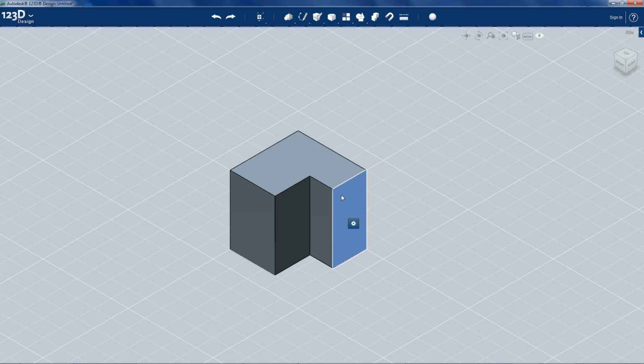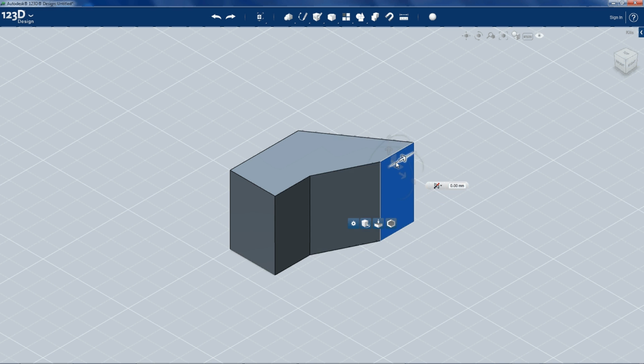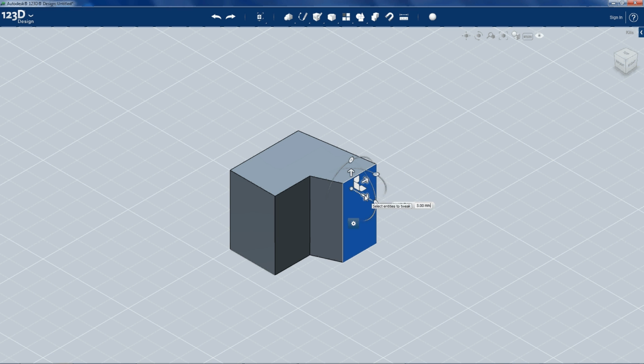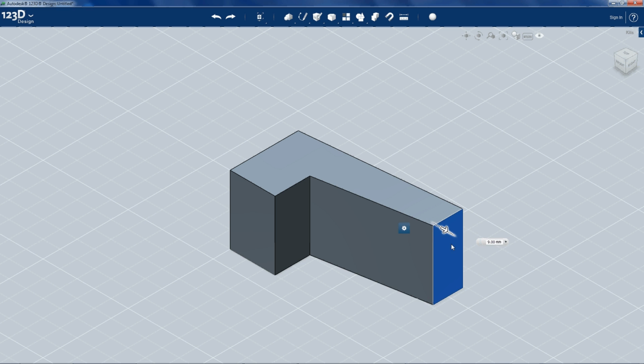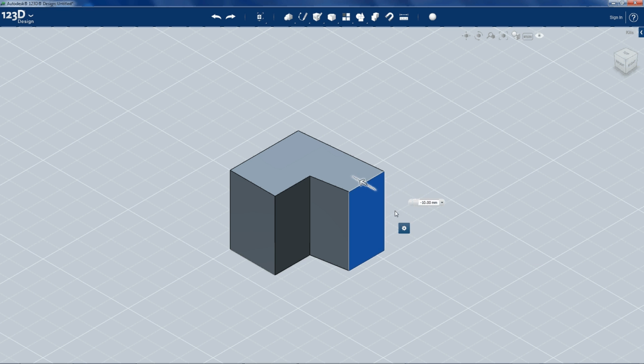So in this case, I'll select this plane, go down to my tool menu, and you see that here's a tool that says tweak. So if I click this guy, I can really do some pretty cool manipulation of this shape. If I try it again, sometimes you have to click twice to get that setting, and I do press pull, I'm kind of extruding from that shape.